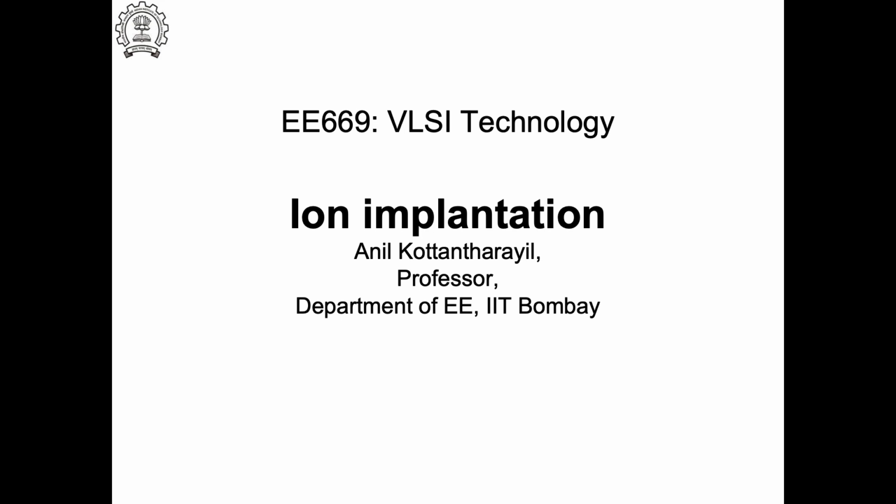Typically ion implanters also break down often. I listened to one of the presentations from Infineon Technologies. They make power semiconductor chips, smart power devices, and so on. In the olden times, they used to also make DRAMs. I think they still make. So one presentation from a production manufacturing engineer there said that in terms of tool breakdown, the ion implanter is the most frequently breaking down tool in the whole manufacturing. So this means it's quite an expensive, heavy instrument. You would not find many university labs which have ion implanters. But you can make a small system using what is called plasma immersion ion implantation. But the capabilities of the tool would be much more limited compared to a beamline implantation.